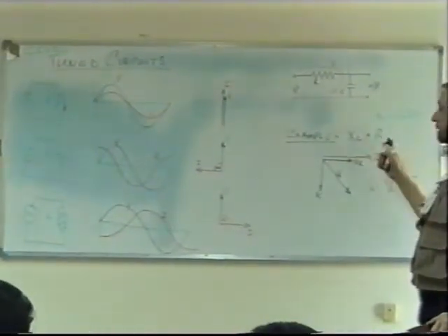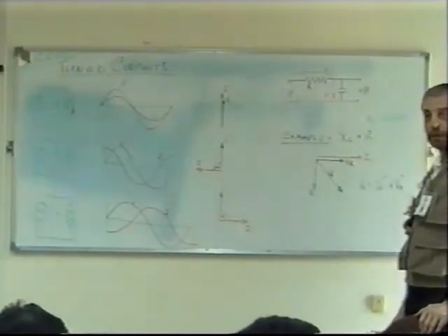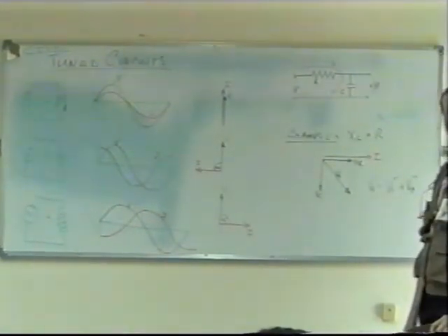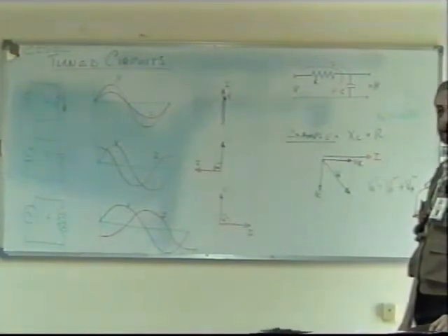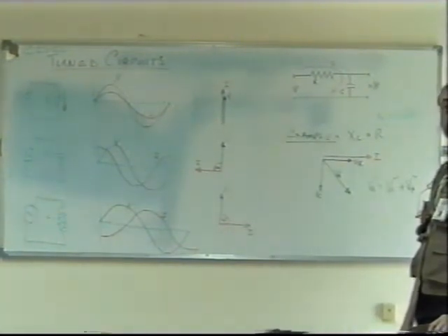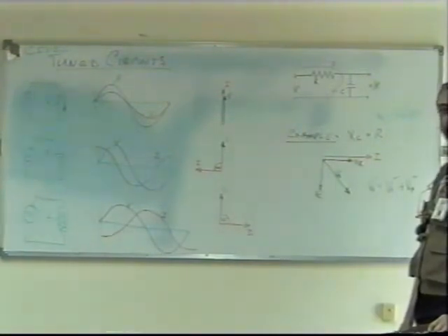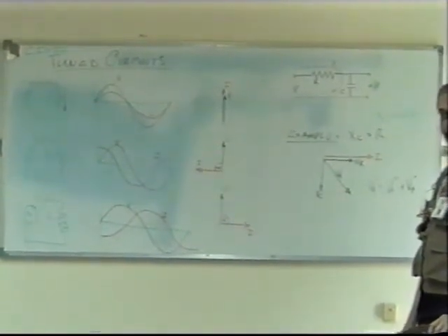If you remember, I mentioned this before when we did electronics and we were speaking about filters. And what did I say that was? At a certain frequency, XC is equal to R. The cut-off frequency, 3 dB frequency, half power. So we're coming back to this again.